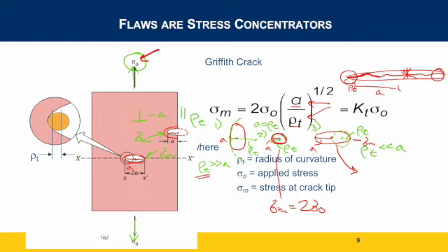They drill a perfect circle with a drill bit. So what they're doing is taking a sigma m that was much, much greater than sigma naught, and turning it into a sigma m that is 2 times sigma naught. So they're reducing the stress dramatically. I mean, it's not going down completely, but they're reducing it, and then they can put in the filler, fill in the holes, and fill in the crack and fix your windshield that way.